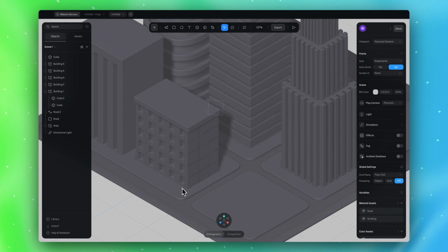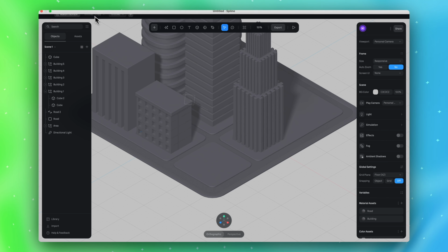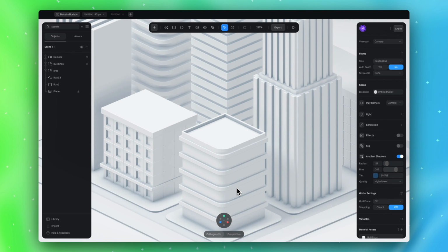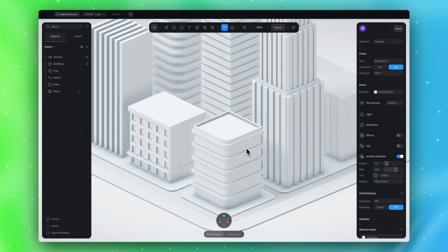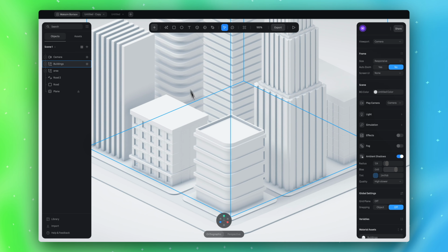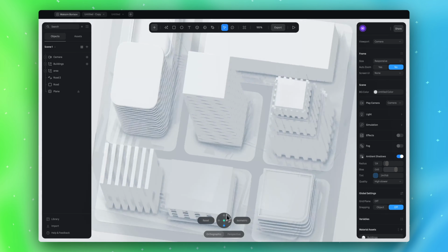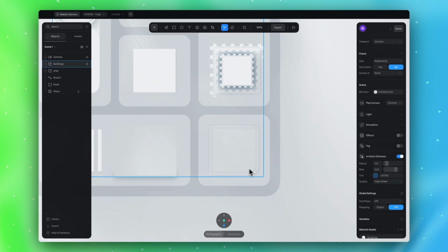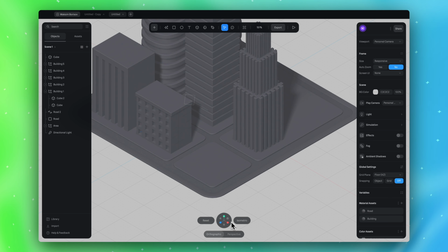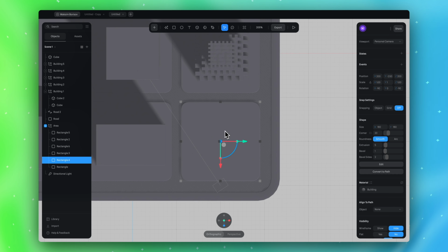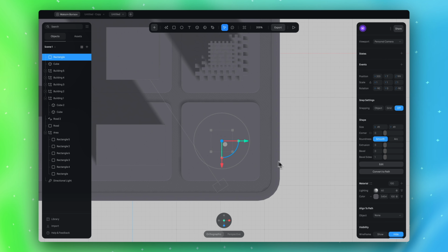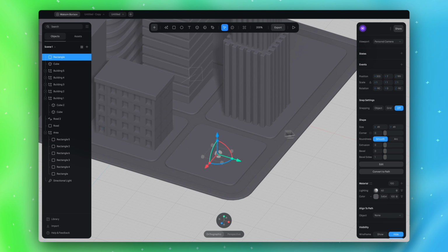Okie dokie. Now let's create this building. So what we have here, again, is the same technique as before, where we have one rectangle as a base and one rectangle with a cloner, which creates these sections, and our rectangle just has a different corner radius. So we can copy this rectangle because this is the area, or we can create a new rectangle which will already be lying down how we need.